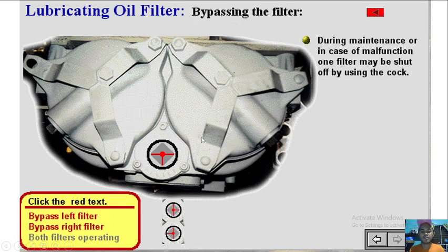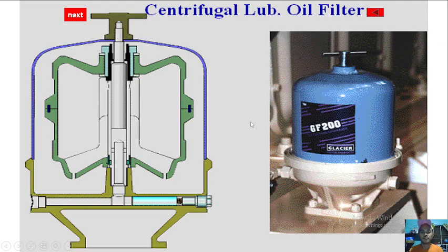We can also bypass the filter if we want. In case of malfunction of the filter, it may be shut off by using the cock, or we can also use both filters. We can use the left filter, the right filter, or both. And also some engines do have a centrifugal lube oil filter.